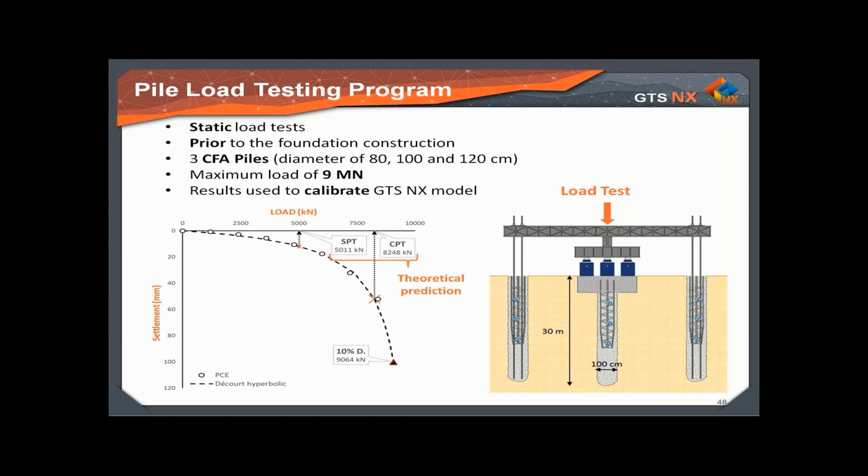As can be seen in the load settlement curve, there is a difference between them, and the prediction of the behavior of the pile based on the CPT is much closer to the measured pile load tests, which is mostly explained because of the nature of the test, which is much more technological than the SPT. In MIDAS GTS NX, the results from the pile load test were used to define the properties of the pile. It is very important to have pile load tests when designing building foundations, especially for tall buildings.